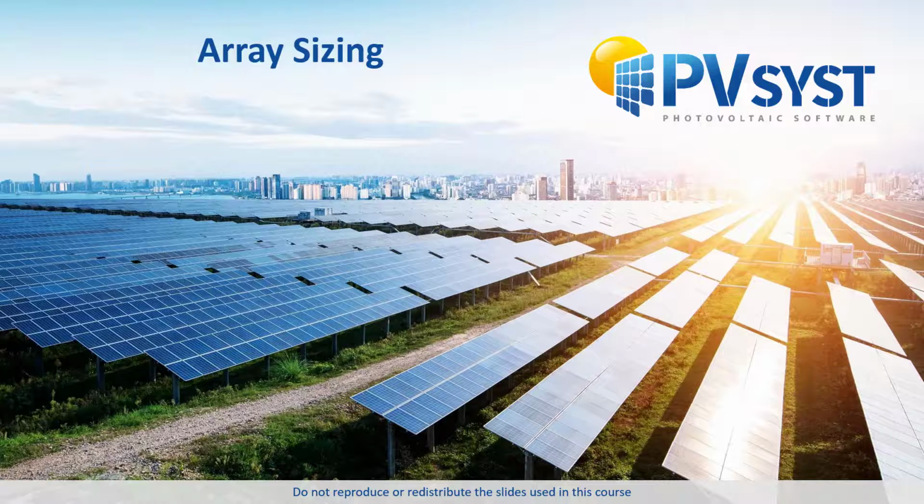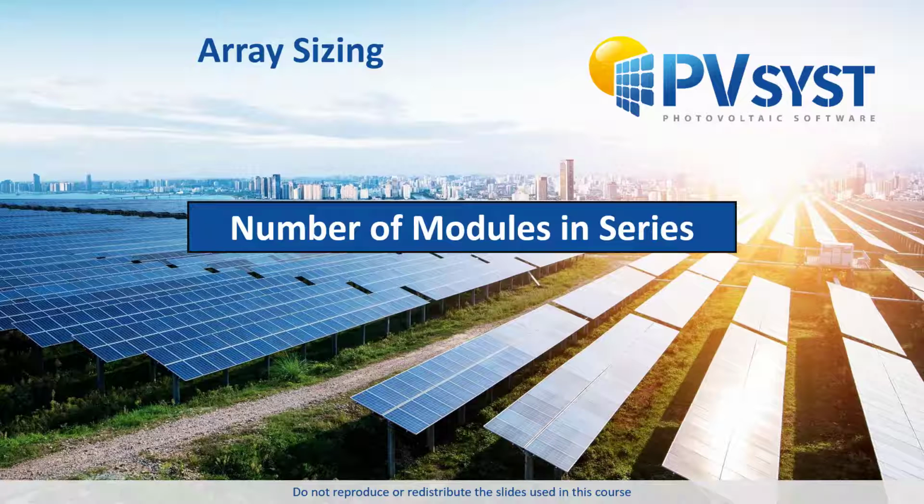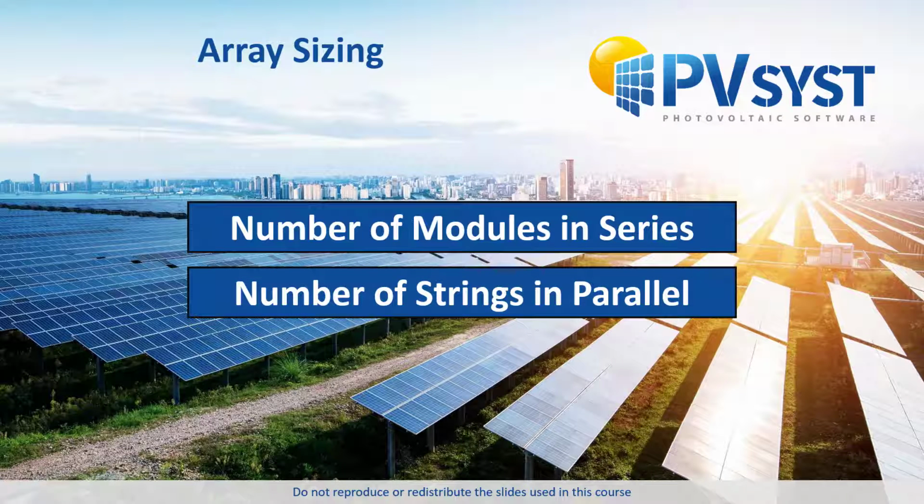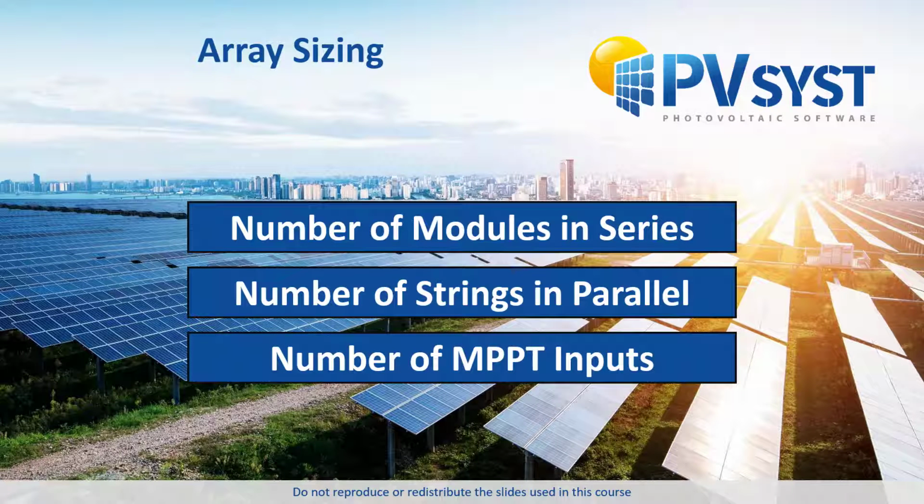The array sizing of a PV system includes the choice of a PV module model and an inverter model. Then, the number of modules in series within a string, the number of strings in parallel, and the number of MPPT inputs to the inverter must be defined. In this tutorial, we will explore the array sizing tool, which helps to define these numbers correctly.